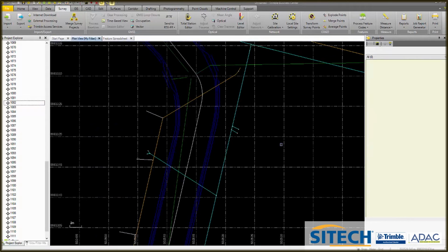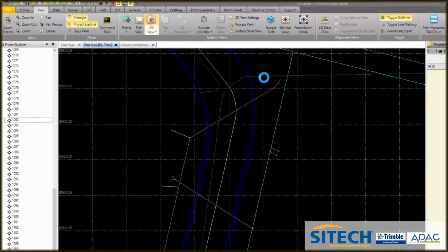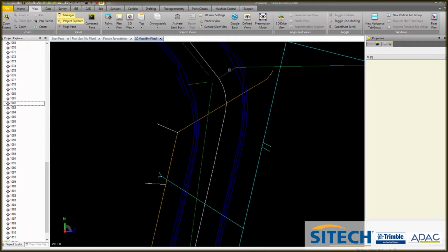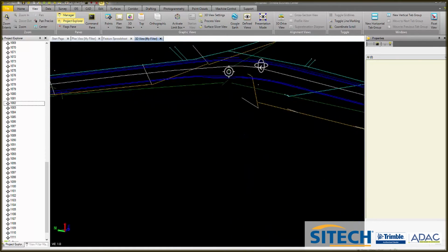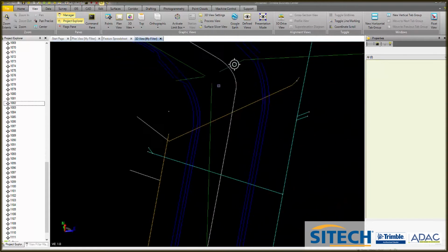Now another thing we can go over is these stormwater lines. We'll just have a look at them in 3D. So go View, 3D. And if you use Alt, you can place a pivot point. Now there's meant to be a stormwater pit here between these two lines.